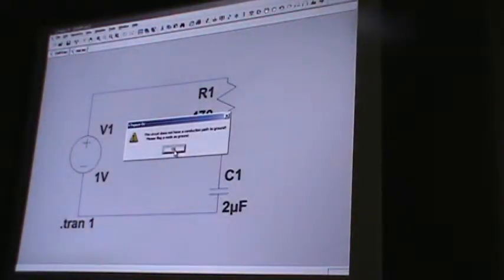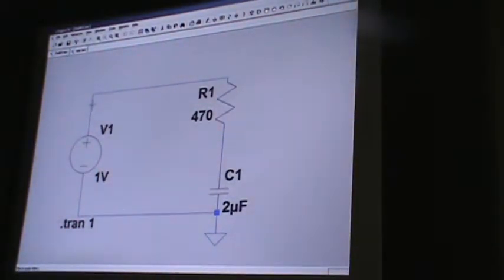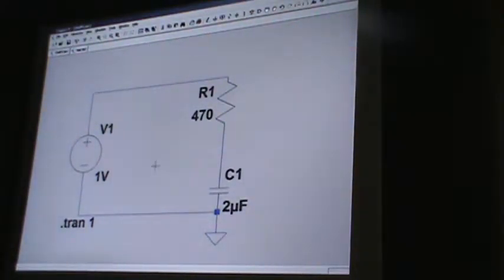There's another little thing. The first of several little gotchas. It needs a ground symbol somewhere. For some reason, it needs some node connected to ground before it will simulate. That's needed for the probe, for your scope, to know where it is. It'll need that to know when you probe various nodes, which node is relative to, and it'll be the ground. Although there are differential probes available too. Okay. I'll get rid of this one.